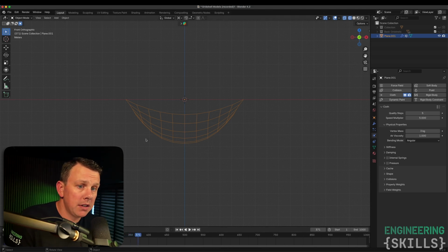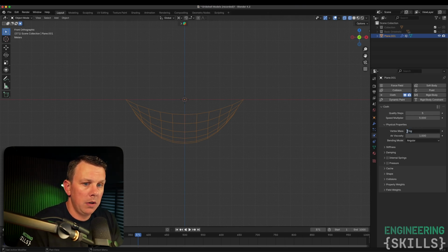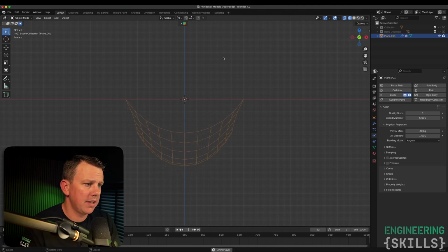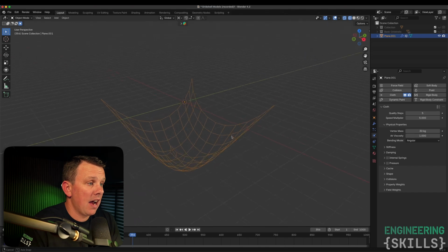So let's say that we wanted to work with this geometry here, right? What I would do, in fact, let's actually do one more. I'll go with 30, and that's going to be the one that we'll sort of run with in this tutorial. So that's 30. We're going to send that back to the start and hit play again. Okay, so you can see it has a significant impact on the shape of the hanging chain. So we're going to just let that come to rest, and it looks like we can stop it there. And so that's our hanging chain geometry.